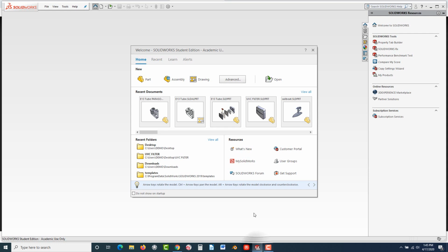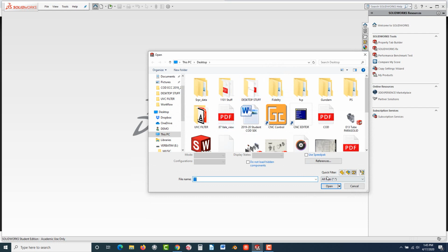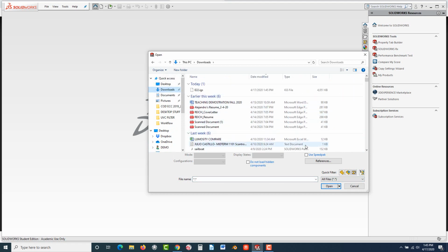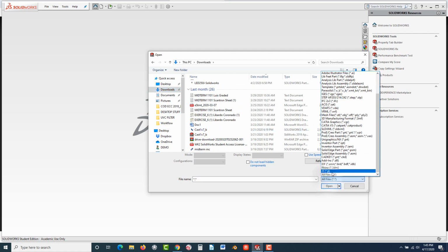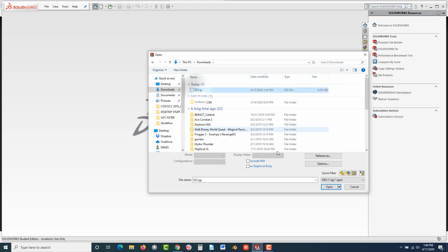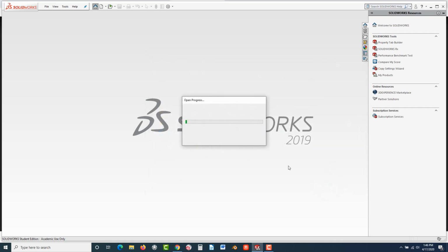What we're going to do, though, inside SolidWorks here, is leave it in the download directory, and I'm going to go to Open here, and change this to the Downloads directory, and we're going to go ahead and find that. Here we'll change the filter to, let's see here, we want IGES. And there it is, E22 IGES. You could click on it and hit Open. And it's going to parse the file, essentially reading it and working its magic as far as translating it in, to try and form it into a solid if it came over as a solid.